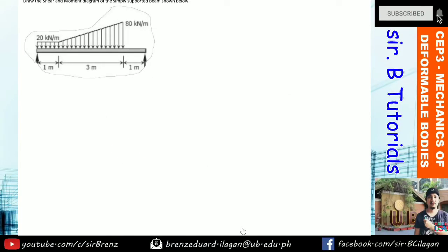Campers. Next problem. Draw the shear and moment diagram of the simply supported beam shown below. This simply supported beam is carrying a uniformly distributed load and a uniformly varying distributed load. So we have here a rectangular load and a trapezoidal load. What I'm going to do here is divide this load into two.